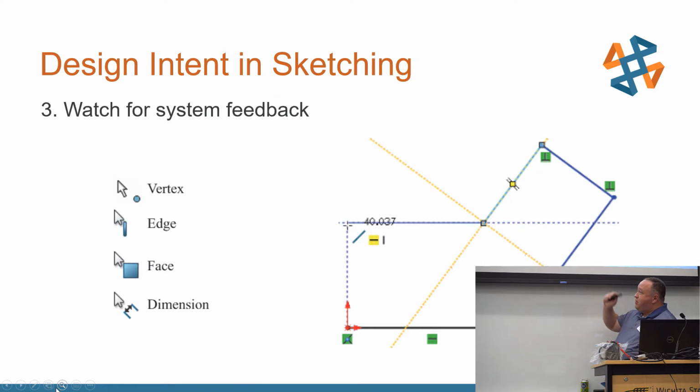Little trick, sometimes, as you're sketching, SolidWorks wants to be a little too helpful and wants to add these auto relations. Do they have that experience? A couple of head shakers out there. Never too helpful, right? Yeah. But, you're utilizing those, or I believe it's the Alt key to bypass these auto relations. So Alt key is kind of a temporary, hey, quick, trying to help, let me do what I want, and then come back when you're done. So nice little option there if you haven't used that before.